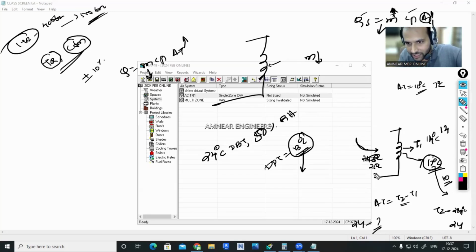Okay, so then this 24 degrees Celsius air will be entering, it will be cooling. Let's say since the delta T is 14 degrees Celsius, the supply temperature might be 10 degrees Celsius in that scenario. But as per our room requirement, the dew point temperature is somewhat near to 13 only, but excess cooling has happened there. That's why the surface temperature of the cooling coil will be too low there.